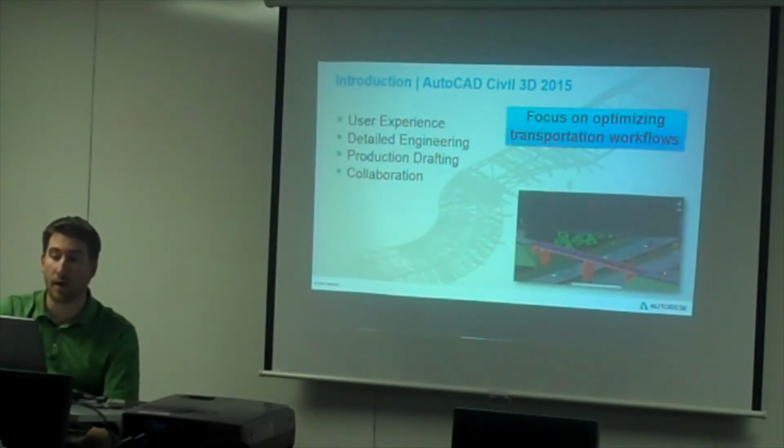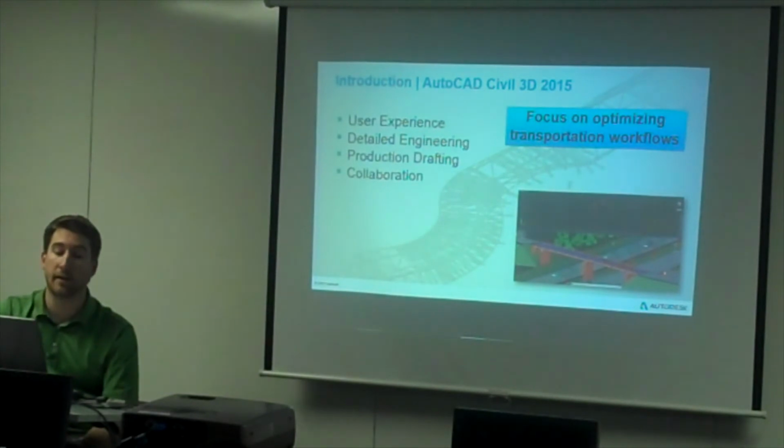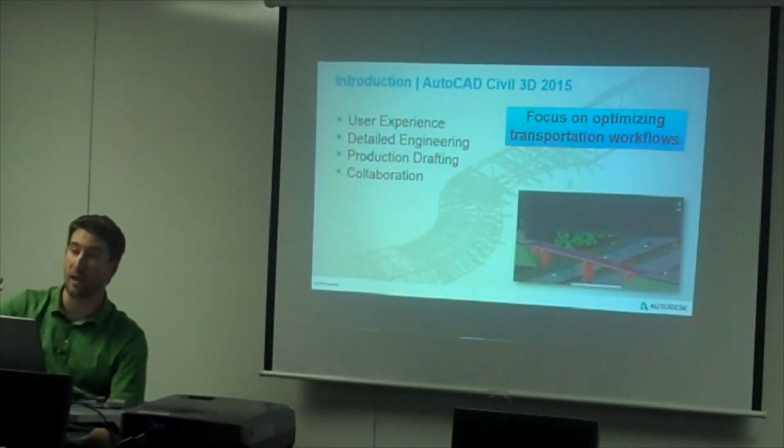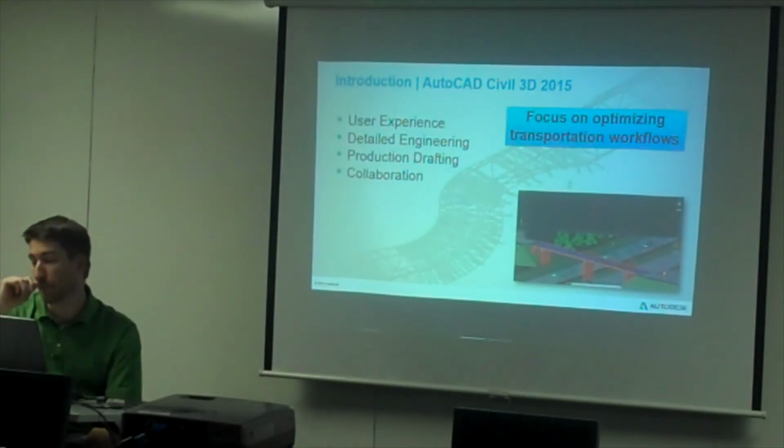If you're doing roadway-oriented activities, it's going to be how you manage and create alignments, profiles, what they call corridors, which is a 3D model of the entire roadway. It includes assemblies, which is sort of that typical cross-section of what the guts of the road are made up of, so that you could quantify that, so you could set various levels of surface underneath that for red tops and blue tops. It allows you to facilitate things like machine control.